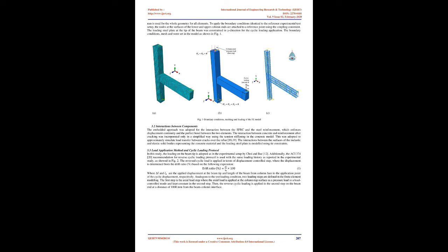Based on earlier studies, the application of SFRC considerably improved the shear strength [8,9], the flexural strength and ductility [10-12], and fracture toughness [13] of the reinforced concrete members. The use of SFRC as a minimum shear reinforcement for beams has been permitted in ACI 318-14 following the research study by Parra-Montesinos [15]. An experimental study of such joint behavior is not feasible to assess the effect of several parameters involved in joint behavior.